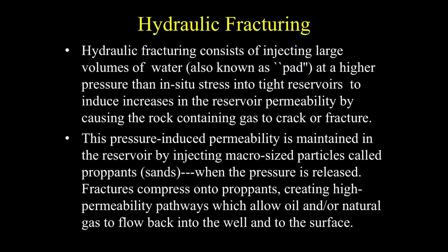Hydraulic fracturing consists of injecting large volumes of water, also known as pad, at a higher pressure than in situ stress into tight reservoirs to induce increases in the reservoir permeability by causing the rock containing gas to crack or fracture. This pressure-induced permeability is maintained in the reservoir by injecting macro-sized particles called proppants when the pressure is released. Fractures compress onto proppants, creating high permeability pathways which allow oil and/or natural gas to flow back into the well and to the surface.